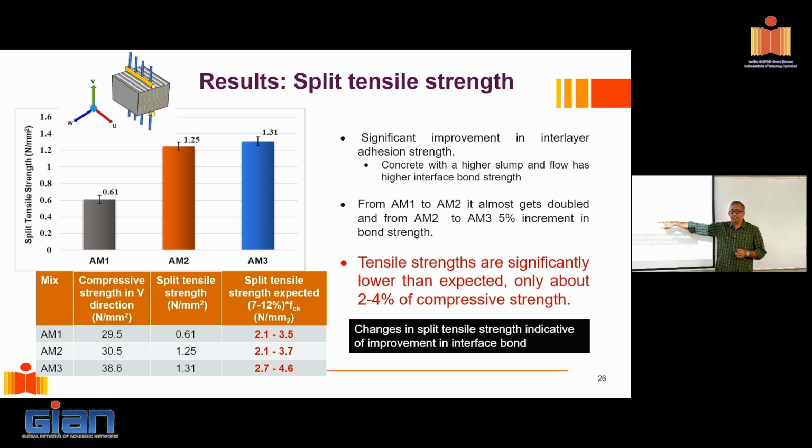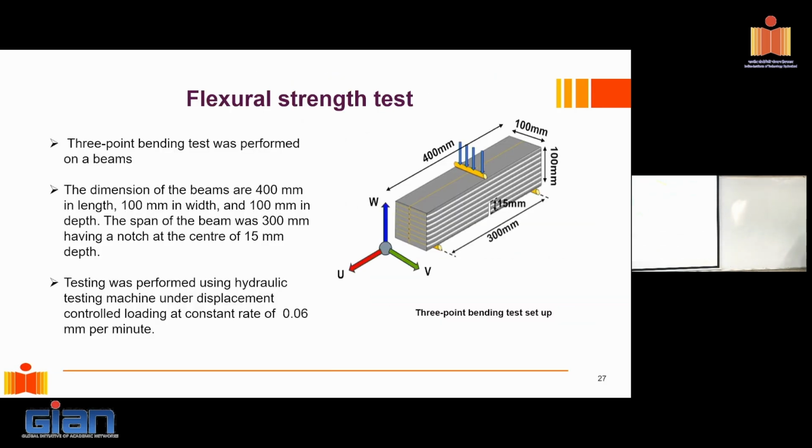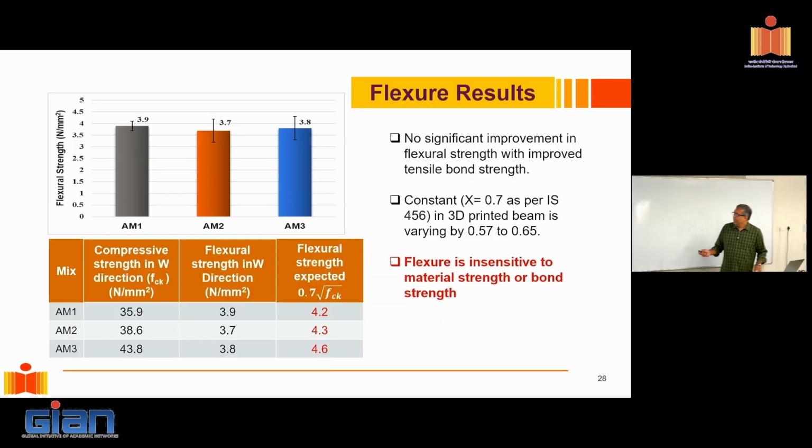Well, first I have to address this issue where I have to come up with alternative math, alternative equations that give me tensile strengths, and the tensile strengths are very low to the point that I may have to completely neglect it. That's the one thing. Flexure is surprisingly robust. It is not sensitive that much. If you get the flexural strength, it's not very direction variant. That's because the layers really don't play that much of a role when it comes to flexure or bending. Whether you're bending in one configuration or the other, it really doesn't matter so much.